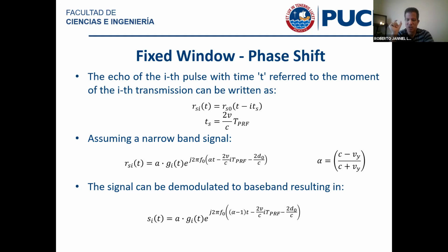That's the change in the phase of the signal because something is moving, right? And that part is the one that encodes the i. It's basically the only part of the signal, in a sense. I mean, of course, there's the G sub i thing, but it's the only part of the signal in itself that carries the information about the fact that I fired my ultrasound transducer for an ith time, right?